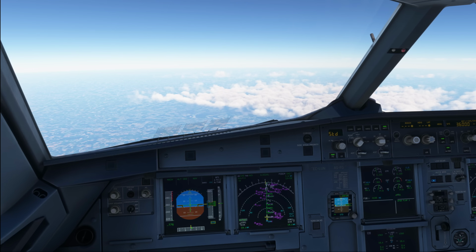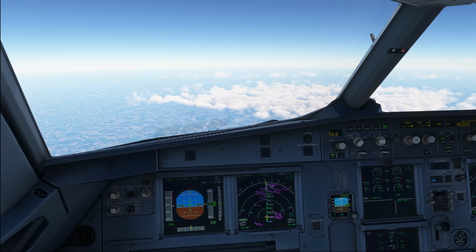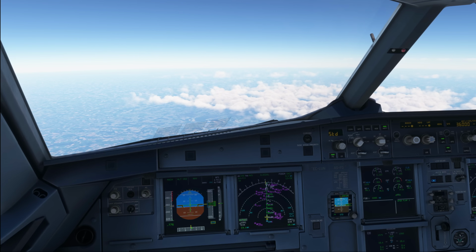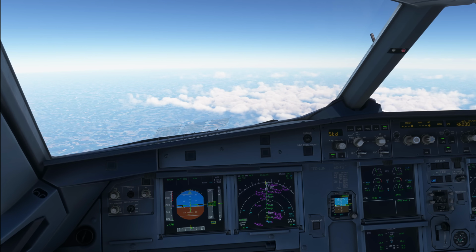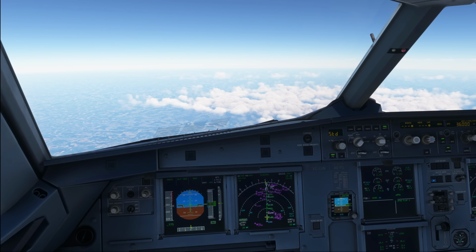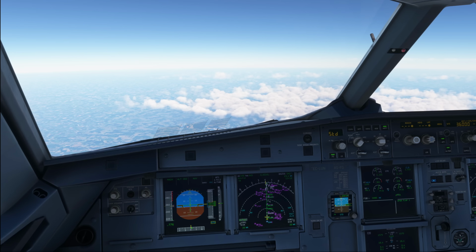Now, when you're preparing for the descent and deciding on the landing conditions, it is recommended to use the following configuration in order to reduce cost. That is landing config 3, reverse idle and auto brake low. Now, if the flight crew needs to reduce the landing distance, they should consider the use of the deceleration devices in the following order. Flaps full for landing as first priority, reverser max as second priority, and auto brake medium as third priority only.